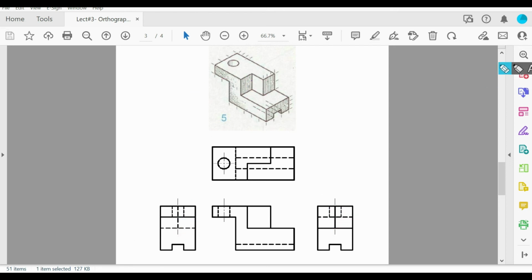Another example, this edge in the left is hidden, which is this one, while in the right view, it is visible. So the relationship between the right side view and the left side view is mirror, but we have to check the edges. Some edges will be visible in the right, and could be hidden in the left, and so on.